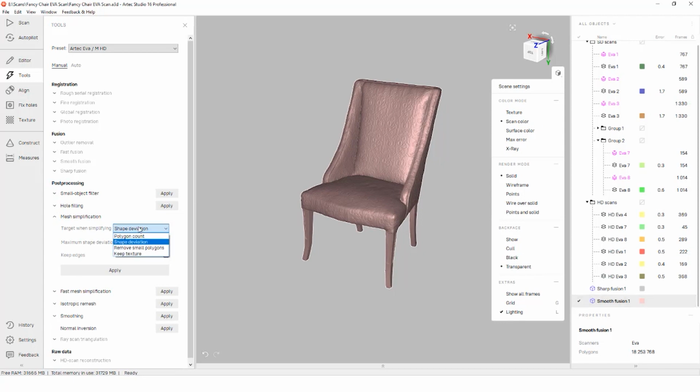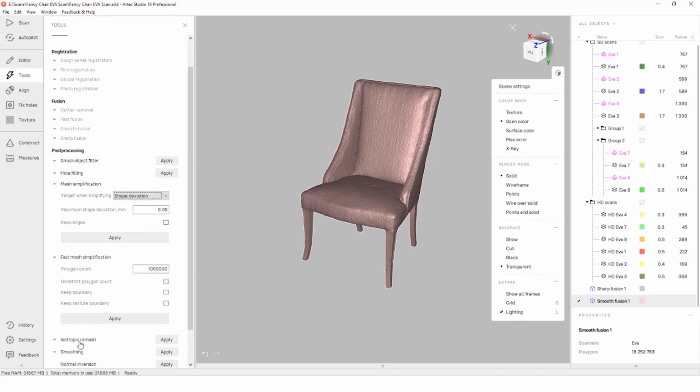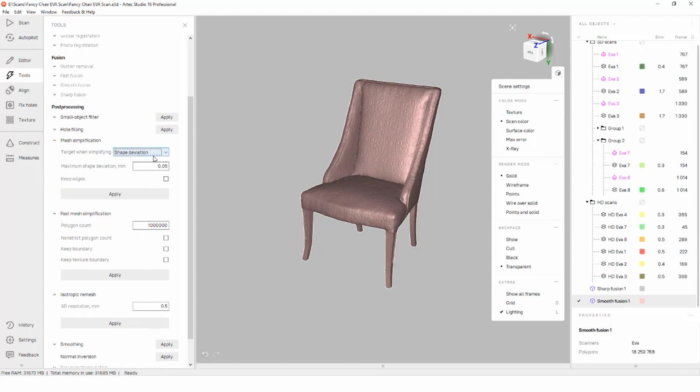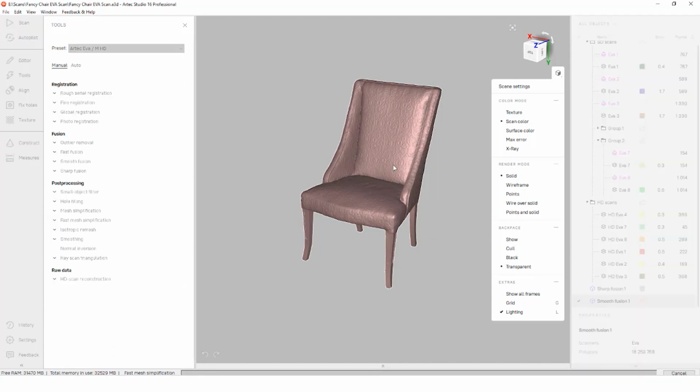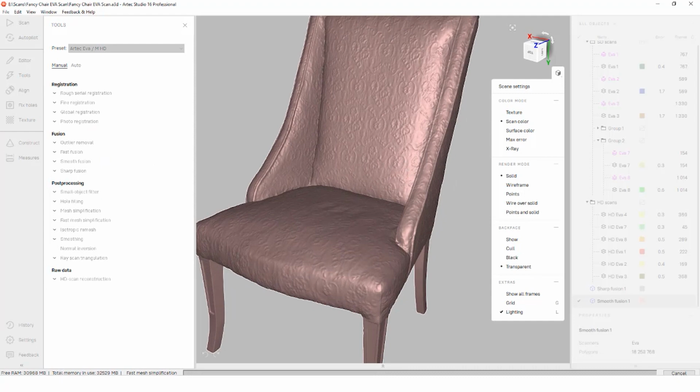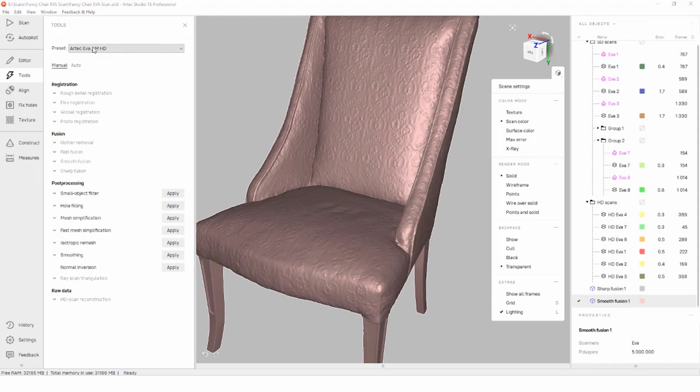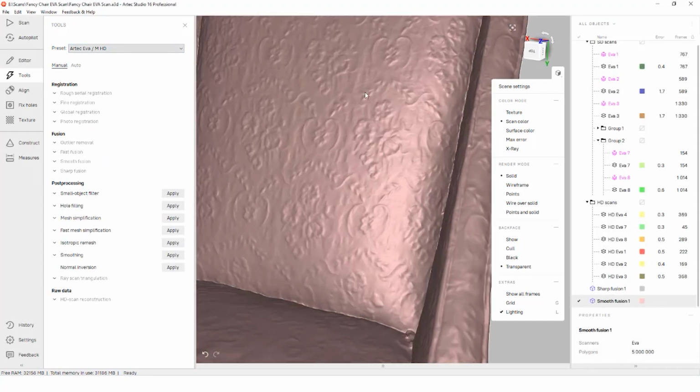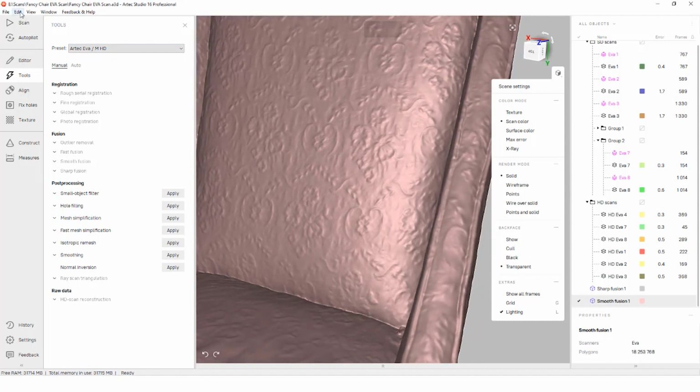The next three settings are related to changing the polygons of the mesh itself. You can check the number of polygons a mesh is by expanding out the Properties tab at the bottom right with our mesh selected. Mesh Simplification has some settings which adjust how the tools check which triangles can be fused or separated. Or if we set it to a specific triangle count, we'll try to reduce it down to that value. Fast Mesh Simplification only has a set triangle count option, and has a different algorithm that will determine how the triangles are changed, but still does a great job.